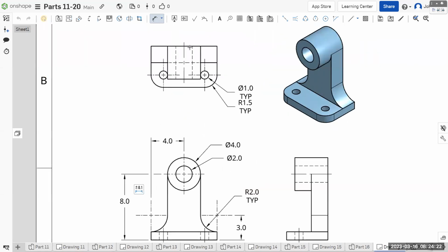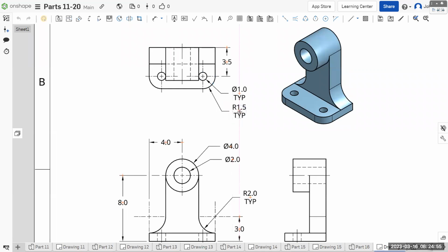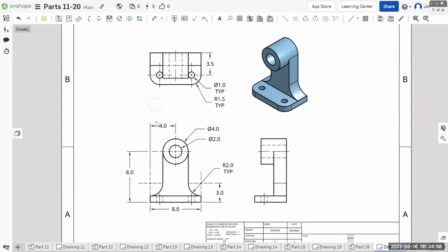Okay, then size and location of the center marks here. We already know their distance to the front because we have this radius. So we just need a way of covering the full distance, which is the same thing as doing the remainder. So that's our dimension this way. And then location, we know it's 1 inch from the side. And we know it's 1 inch from the side here, so we don't need those other dimensions. So many of the dimensions are inferred based on what's already there.